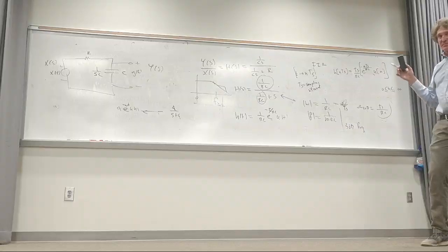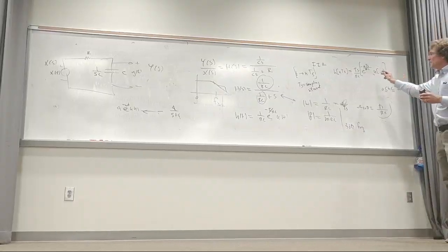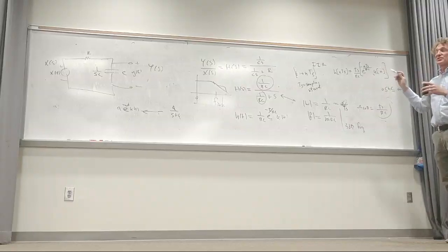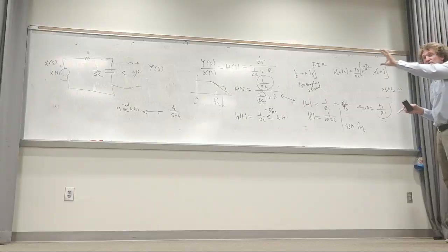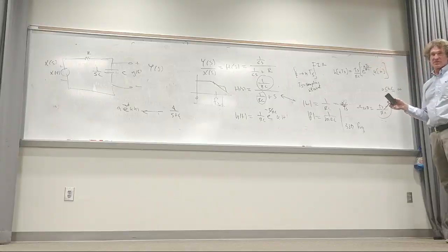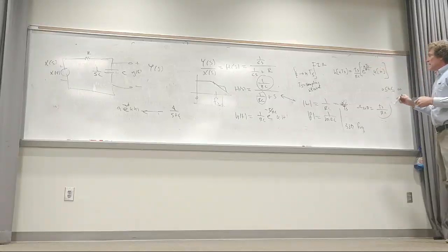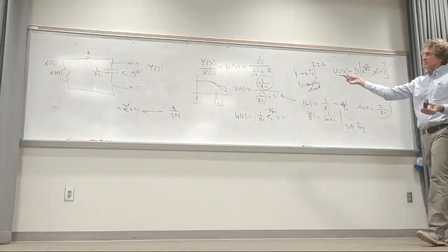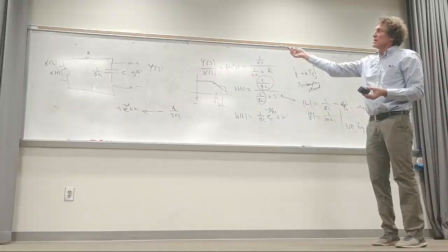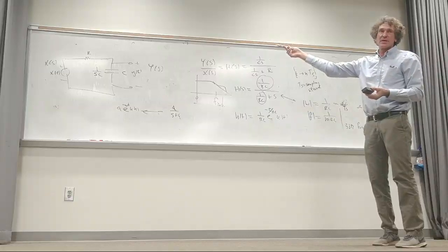You'll find out, this is the bottom line, if you took 11 terms here and you did convolution, just like we did before, you would still very clearly see the 0.7 pi n signal, cosine of 0.7 pi n, where the original filter we did got rid of it completely, just about. I mean, there's a little risk. This method is easier to use because that's a 20 dB, and I'll show you a filter with 40 dB in a second.